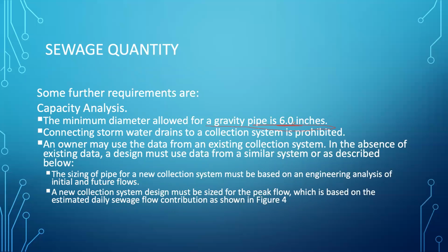So any smaller than that, you get teddy bears stuck, along with golf balls and other small stuffed animals that find their way into the toilet and out your system. And so they selected the minimum pipe diameter to be able to convey the largest blockage that they don't want to have to deal with.